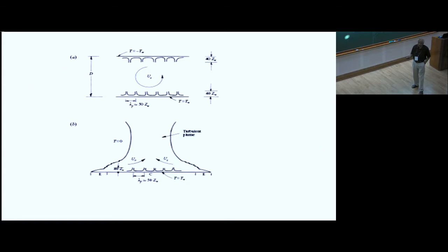And this is the basic message, that the near wall flow on any horizontal convection would be composed of these line plumes with a typical spacing of about 50 wall units. So that is like what you would say in turbulent boundary layers, where it will be about 100 wall units, of course. And the type of structures there are very different. And similarly, the same type of structures you would get on a horizontal isolated plate as well.